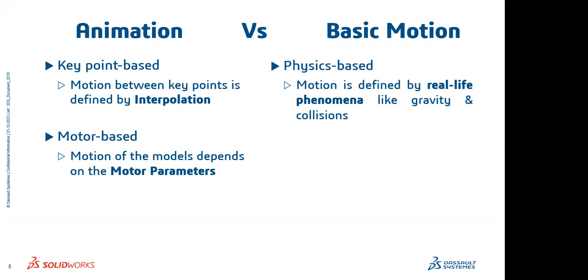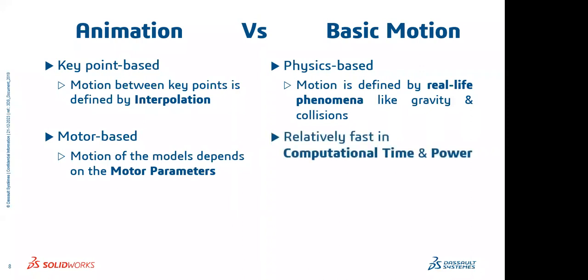On the other hand, basic motion is more like simulation, right? Because here it's got physics involved, whether it's gravity, whether it's contact, that kind of stuff. When you talk about simulation, it's usually computationally intensive, and it might take so much time to calculate. But that's actually when it comes to motion analysis. Basic motion is like a stripped down version of that, where it's got some sort of physics based on it, but it doesn't take that much time to get your animations calculated.